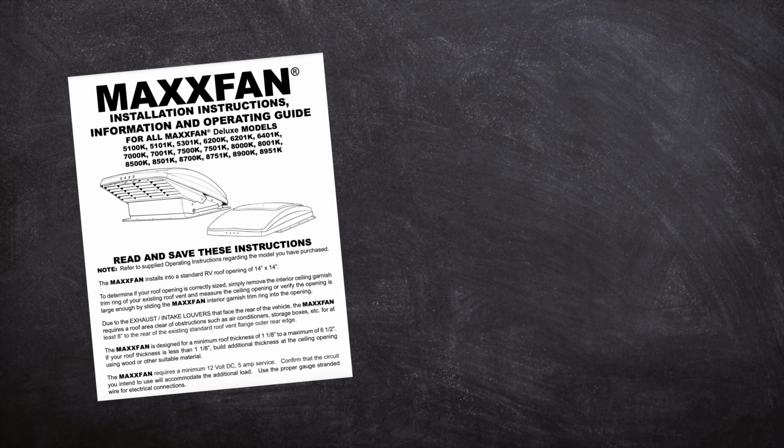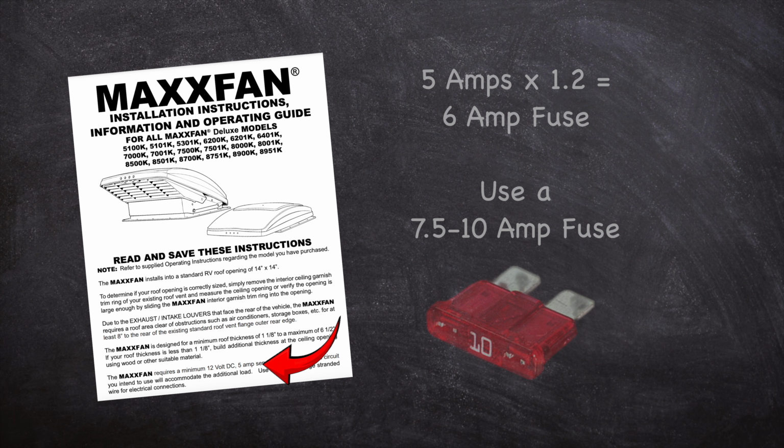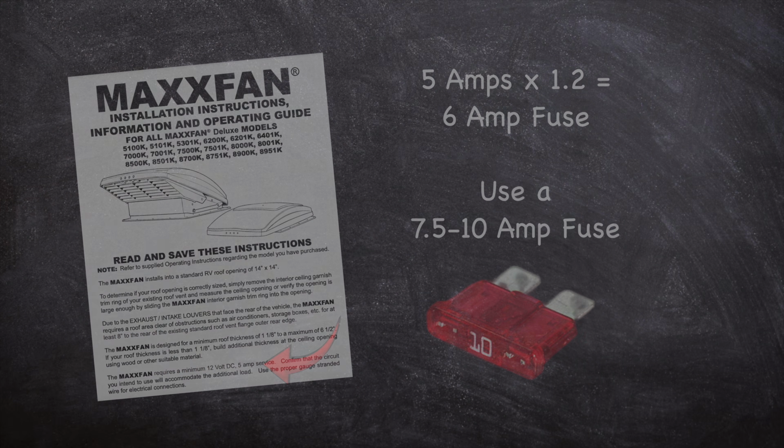Each fuse size was determined either according to the device manufacturer's recommendations or by multiplying the device's continuous amperage by 1.2 and rounding to the nearest available fuse size. However, when rounding up, do not exceed 150% of the rated wire ampacity.